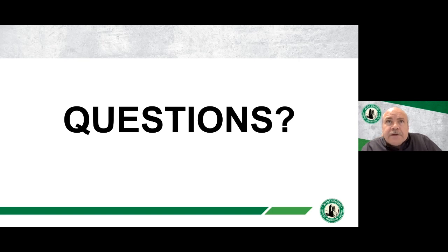That's a good question. A lot of my answers for GPR is it depends, because it really does. Under ideal, dry, granular conditions, some of the low frequency GPR is very successful at getting data 8 feet deep, 10 feet, 12, even 14 feet deep. Now, if it's a saturated clay or silt, that's going to be reduced.